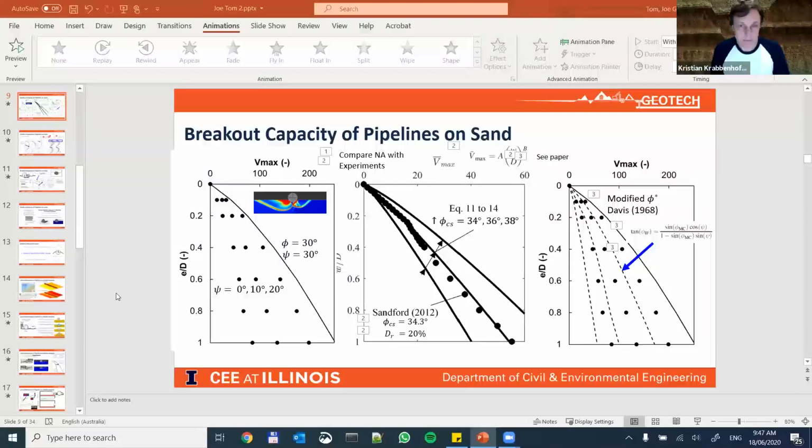And I would say, I don't know if that's your experience, but for shallow problems like this one that you're showing there, the Davis approach tends to underestimate the capacity, and for more highly confined problems there is a tendency that it'll overestimate it. Yeah, yeah. Sorry, overestimate for the more confined problems, and underestimate for these shallow problems, yeah. Yeah, that's pretty much it.